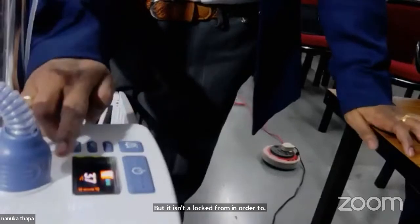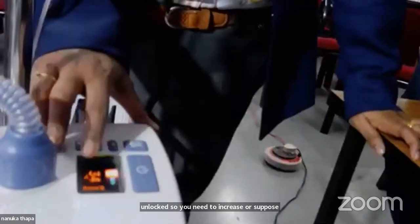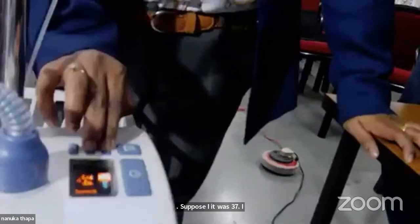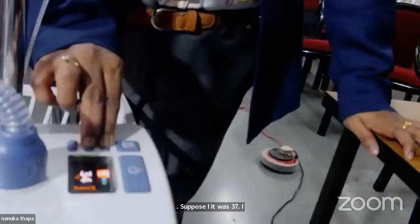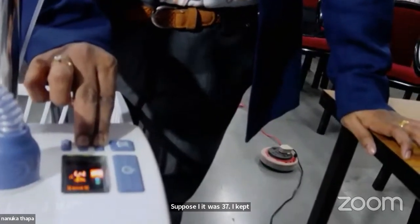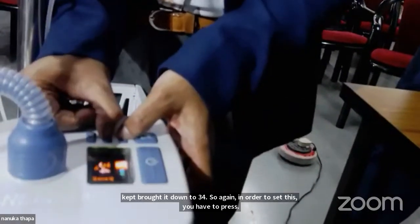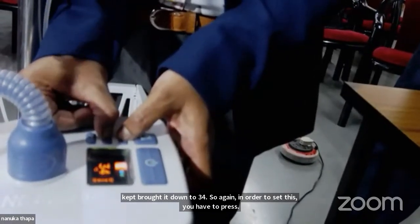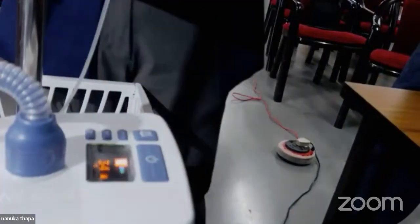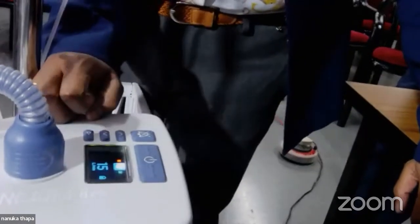So you need to increase or decrease. Suppose it was 37, I brought it down to 34. So again, in order to set this, you have to press the up and the down arrow together. Play button. So this is done with the temperature. Now next is the flow rate.